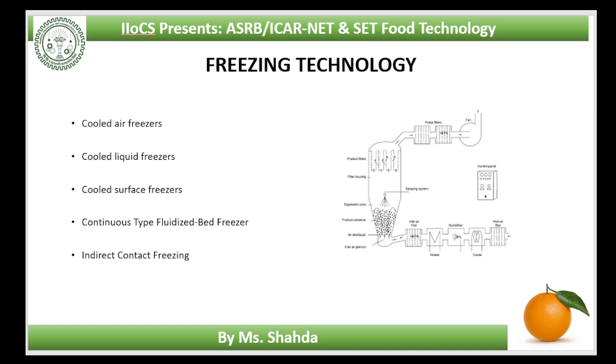Liquid nitrogen is manufactured by compressing air and simultaneously removing the heat of compression. The cooled compressed air is then allowed to expand through specially designed valves. This expansion causes further chilling.